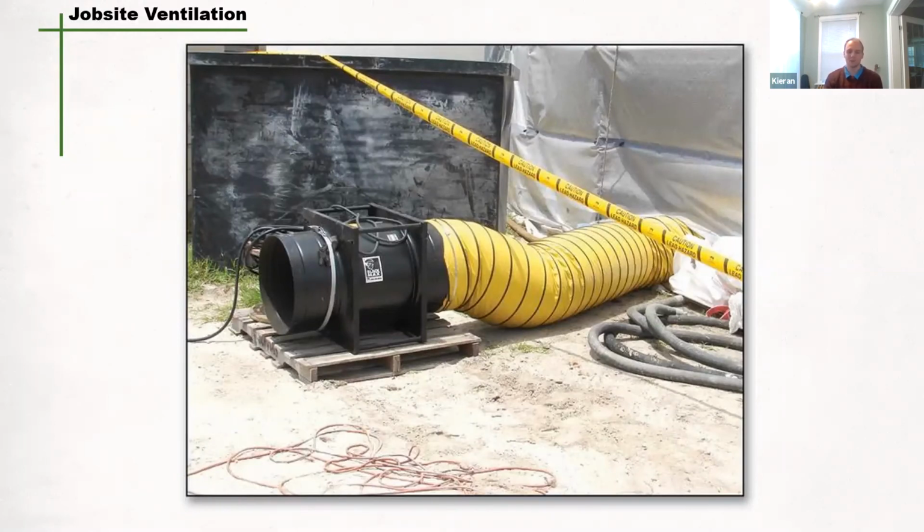So a lot of thought must go into a system like this. Generally, a qualified person, an industrial hygienist, or someone with the training will design a system that removes enough air and has enough dilution for a certain area. But oftentimes these systems are going to look like this, a fan with a big hose.